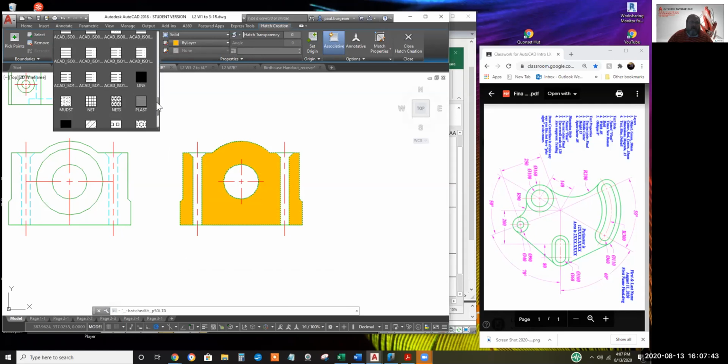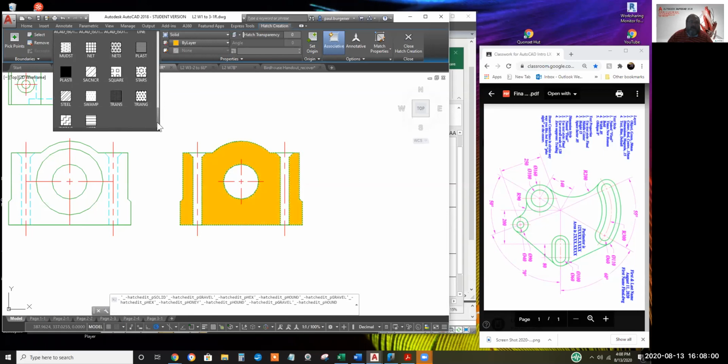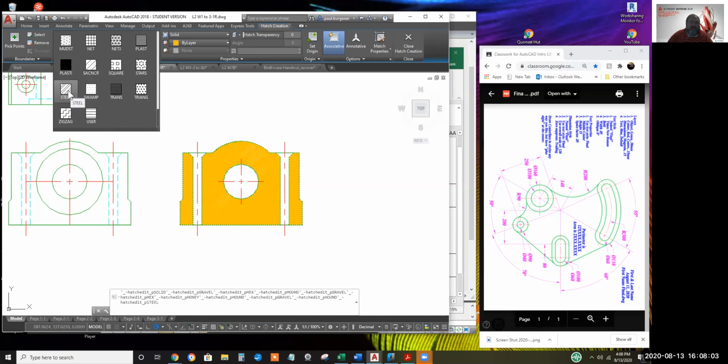Now, before I select one, keep in mind that these swatches, or these wallpaper samples, if you will, are not all drawn to the same scale. The crosshatch patterns for the metals, steel, I think there's one for aluminum, or aluminium as they say in Britain. I think ANSI 32 is aluminum. ANSI 31 is steel now. No, that's cast iron. I don't know what these others are.